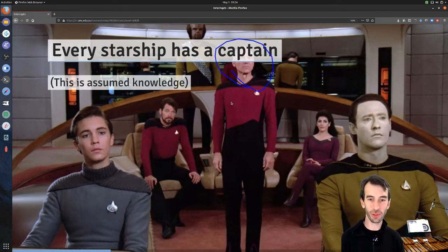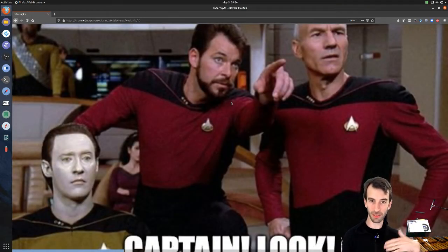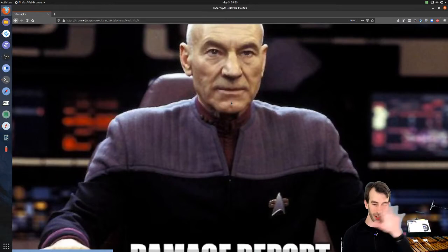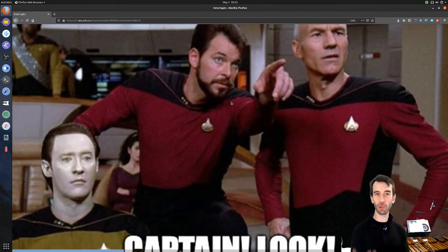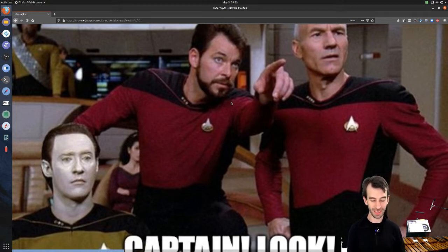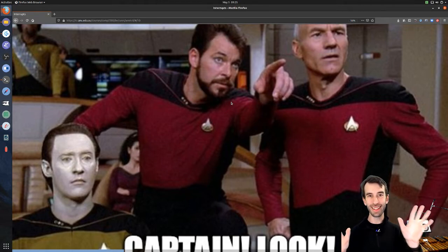Now we can look at these two ways of getting sensor information as two different styles of handling communications. The first one, where he's going around the room asking everybody what they're up to, we could call polling, right? So the CPU, or the program in charge of the Starship or the computer, is going to go around to everyone who could potentially be giving us information and say, okay, what's on long-range sensors, what's on short-range sensors, what's the engine status, what's the weapons status, getting all the statuses, and now we've got all the information. And this other style, where someone else can temporarily take control, do everything they need to do, and then we return back to our normal operation, would be the interrupt style. So these two styles: polling and interrupts. Okay, we can call the analogy time over for the moment